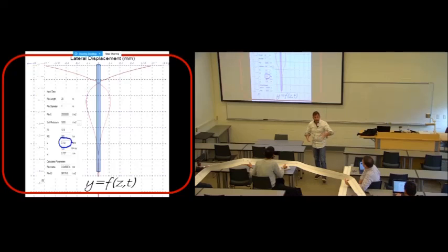Why do structures fail when they are on clay? Because the wave comes, and let's say it's transmitting from the rock at high frequency, and then hits the clay, it becomes high amplitude, it amplifies.